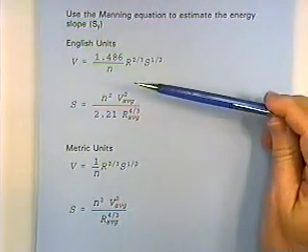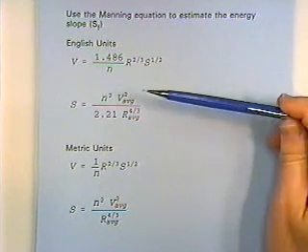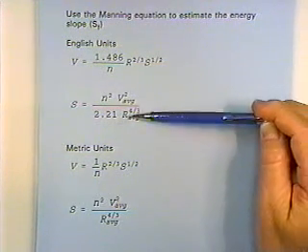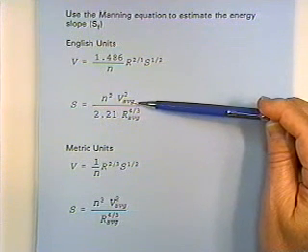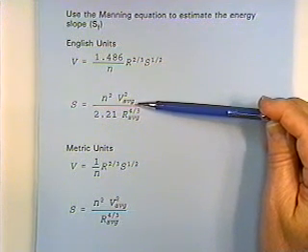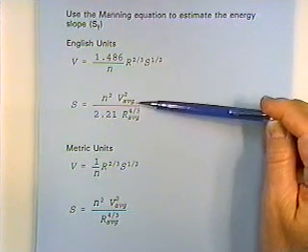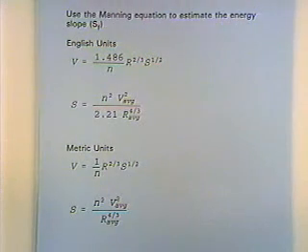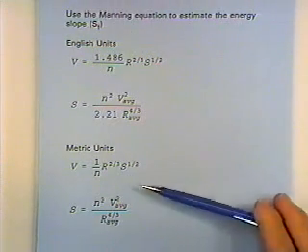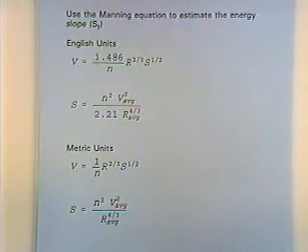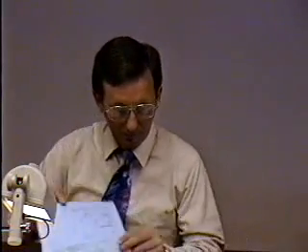And the thing is, what velocity do we use? The velocity is different upstream and downstream. What hydraulic radius do we use? It's different upstream and downstream. Well, we'll approximate the velocity as the average velocity, just the average of the upstream and downstream, and average the hydraulic radius upstream and downstream, and use the subscript average for that. If we wanted to do this in metric units, it's the same thing, just the constants are different. So that's it, and we'll go through it now in the context of an example problem,